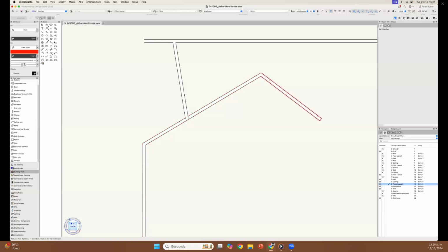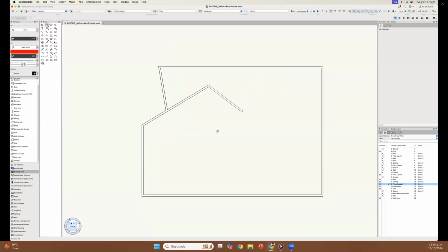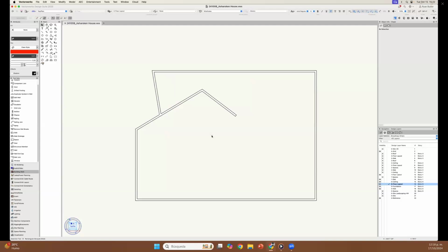Now we did an L shape here, there's an L shape here, let's do an L shape right there. Now let's do a T shape. So if we do a T shape, you just click this one up here, click this first, then this one, and then that's that. Now this is great for just quickly drawing walls to get your point across, to get your building laid out. Now also if you wanted to move the wall, you can do so and the walls will stay together. So let's say if you want to change this wall type, or wall style, to something else, to something more specific.